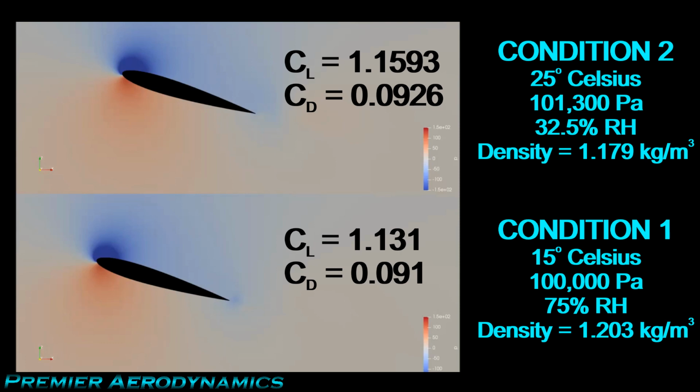Now again, these are pretty close to what they should be because the velocity is very close to 15 meters per second. It's 14.9 for the bottom one. For the top condition though, we don't know that these velocities are different because we haven't measured the density, but they are. For the top one, you measure the forces and assume that the velocity is 15 meters per second and the density is 1.2 kilograms per meter cubed.